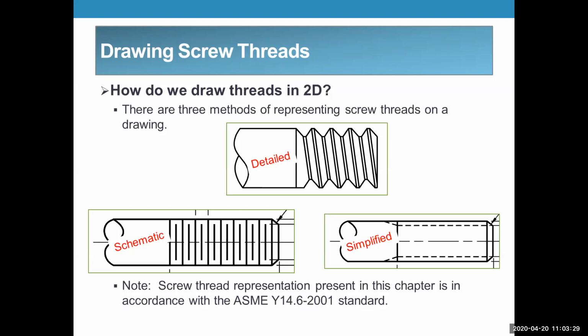to an accurate distance. Usually, when you draw it, especially by hand, if you put a chamfer on it like this, this is where you start that dotted line, the hidden line. You start it right there and just draw it out to wherever you need to, and that's that. Because it's simplified.